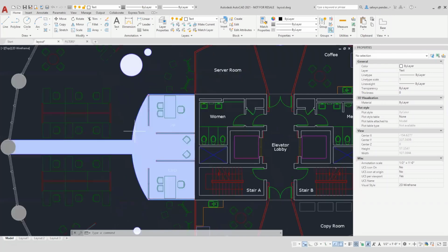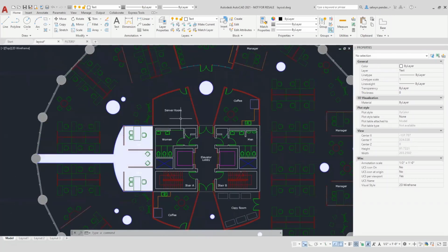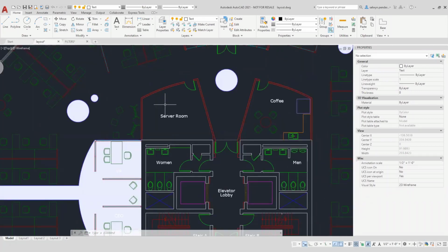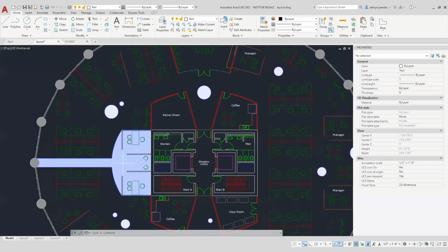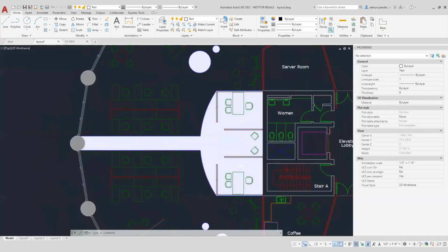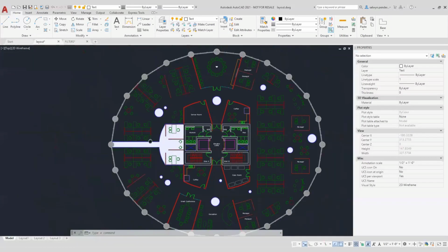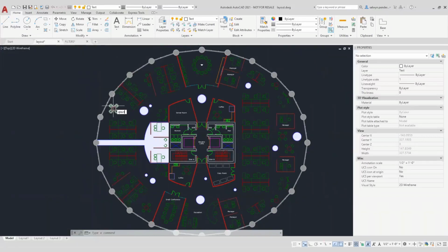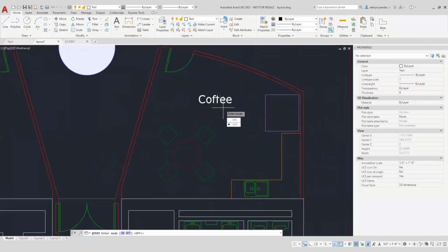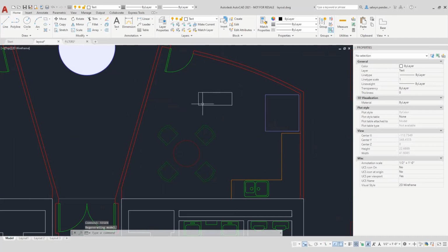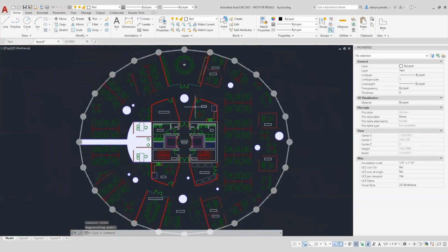When we have a drawing, we might find that we've got a lot of text in our drawing and it's slowing down the regeneration, or we might have hatch in there and we want to be able to see through the hatch. There's two commands. There's one called Qtext. So if I type Qtext at the command line or at the cursor, I have the option of turning it on and off. When Qtext is turned on, the text will become rectangles. So I'll turn Qtext on, regenerate, R-E-G-E-N, and now all the text in the drawing will show as rectangles.